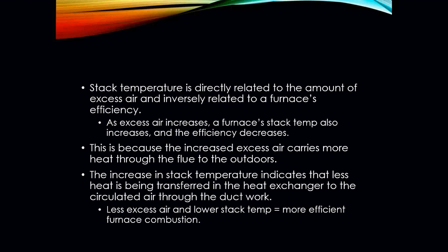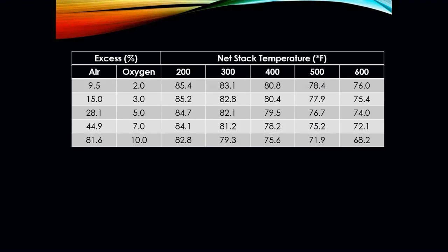The increase in stack temperature indicates that less heat is being transferred in the heat exchanger to the circulated air through the ductwork. Less excess air and low stack temperature will equal a more efficient furnace. So there is your key to getting your piece of equipment at a much higher efficiency: less excess air and lower stack temperatures.